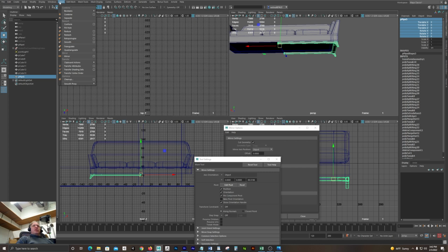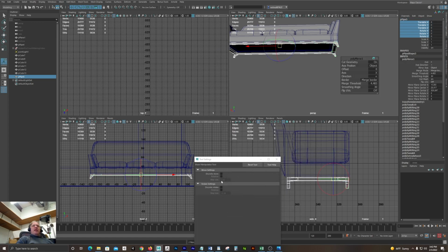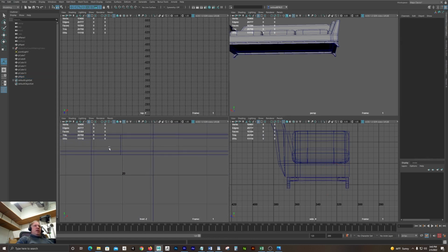Mesh. There's my window already there. I just hit mirror. Boom. And since automatically merge is on, it merged these. I don't have any border edges there. Just that one edge loop where it fused itself together, and I want to get rid of that edge loop.